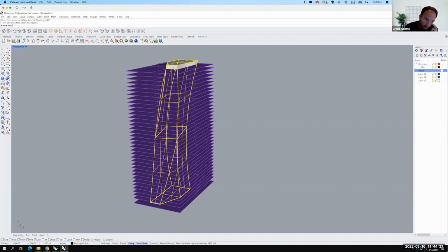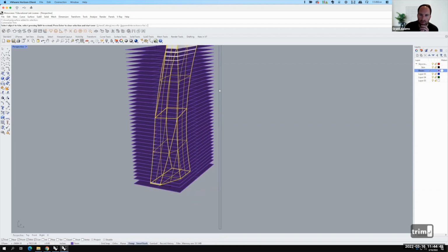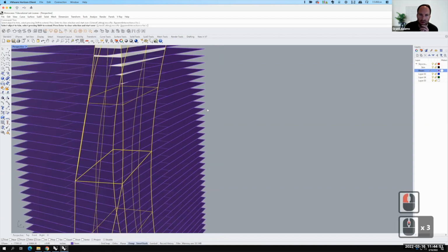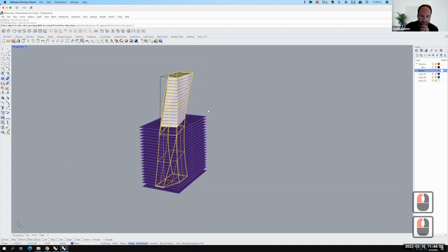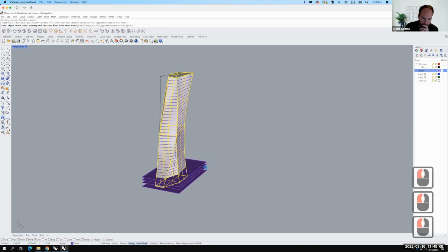Okay, so what I'm going to do is trim this. I've selected my skin, and then I'll type in trim, or go up to Edit and then Trim. While it's tempting to just do a big rectangle and trim them all at once, sometimes that crashes. So I like to do smaller groups. I'll trim a few at once. I didn't trim the last one because there actually already is a base. So we'll go ahead and hit enter.